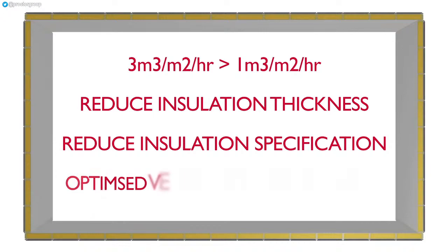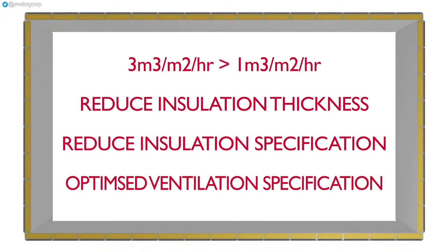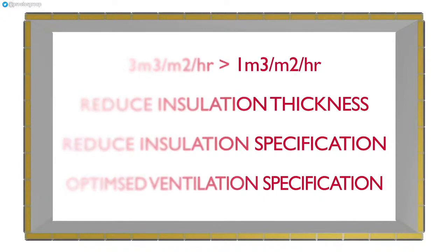If implemented in the design at an early stage, this enhanced airtightness does not lead to the building requiring complex mechanical ventilation systems, as other options such as passive ventilation strategies can be implemented. We can, however, only take full advantage of this flexibility if we can depend on achieving the air leakage targets that we use in the design process.